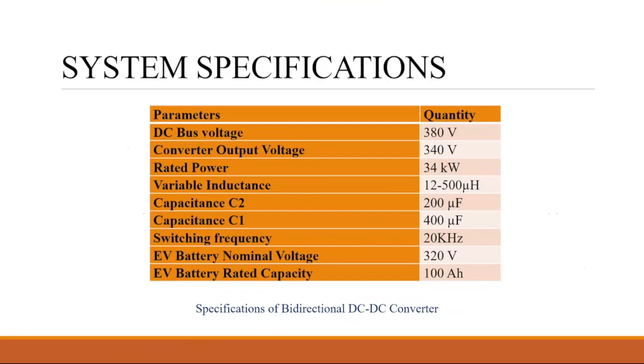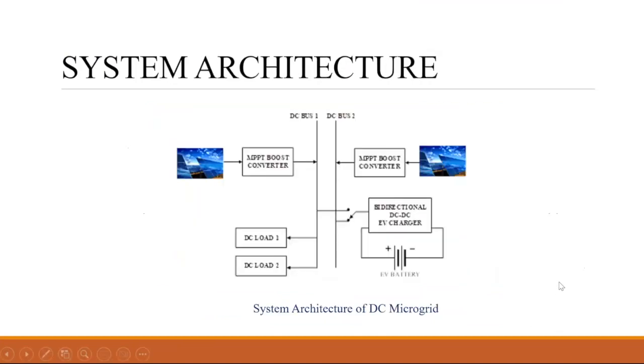Okay, so yeah. Now moving further, this is how our system architecture looks like. I just wanted to tell you what the application of solar photovoltaic systems is for our application, right? This is a solar panel, this is a charge controller, this is the DC bus. These are the loads. There is another system, and there is a bidirectional charger. So in the daytime, what is happening? The car is getting charged, the system is getting operated. Okay.